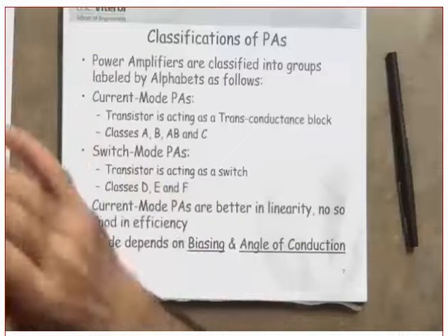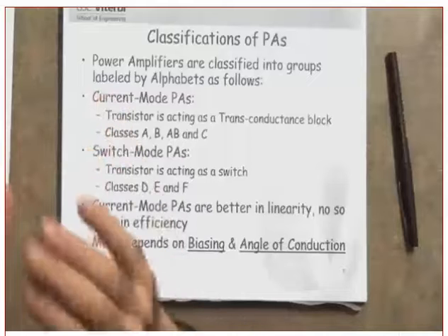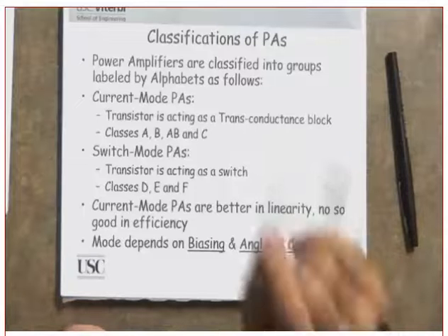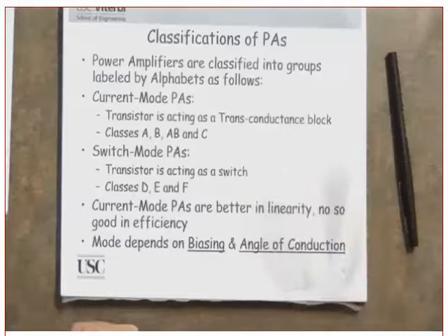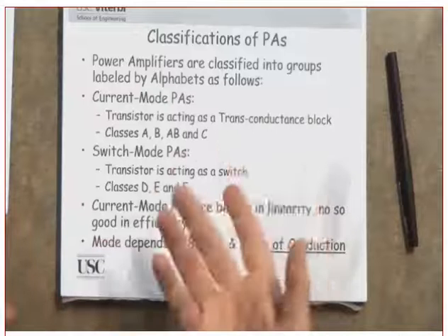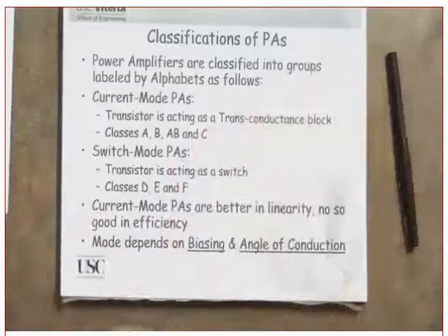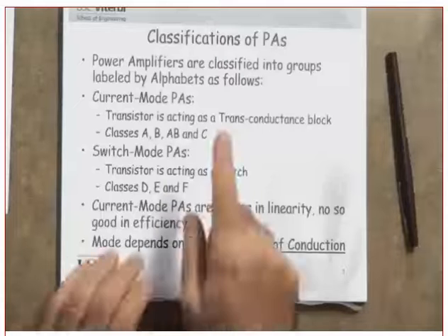If you are operating your MOSFET as a switch, you are going from which mode to which mode? You are going to go from the off mode to the triode mode, without stopping, or at least just quickly going through the saturation mode. But if you are operating it as a constant current source, you are operating in the saturation region. Clear? As we'll see in just a second.